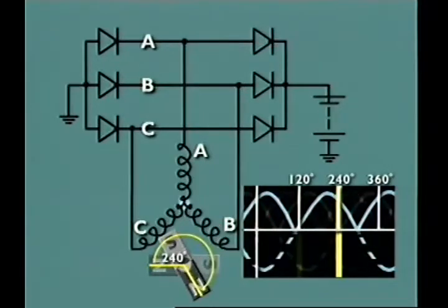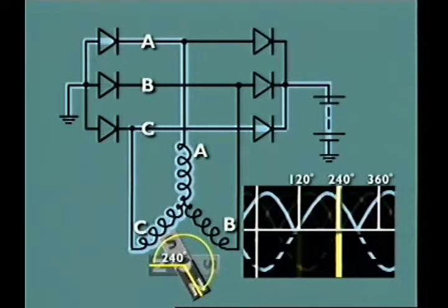When the magnet rotates further to this position, the polarity of winding A changes. The current path then is winding A at star point, winding C, positive diode C, alternator terminal B plus, battery positive terminal, battery ground, alternator ground, negative diode A, and output of winding A.